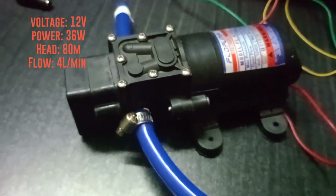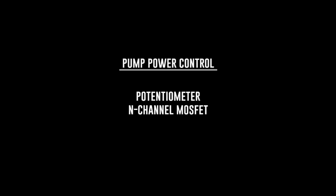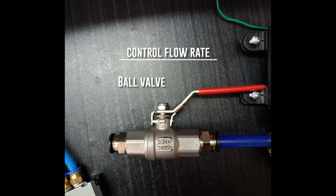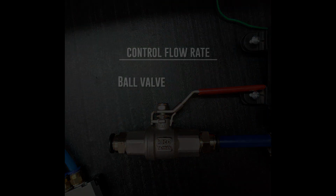The power of the pump needed to be controlled according to our requirements, for which we used potentiometer and N-channel MOSFET. Apart from power, the flow rate of pump needed to be controlled as well because the loading rate depended on flow rate. For that we used a ball valve which regulates the flow rate.